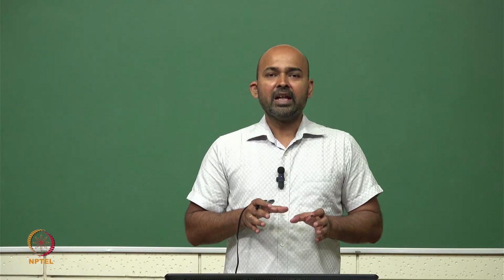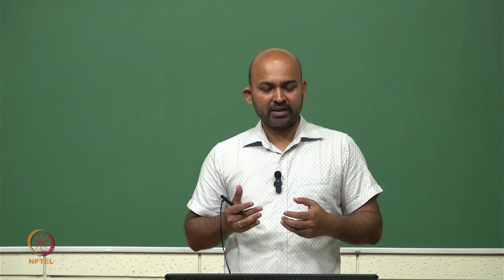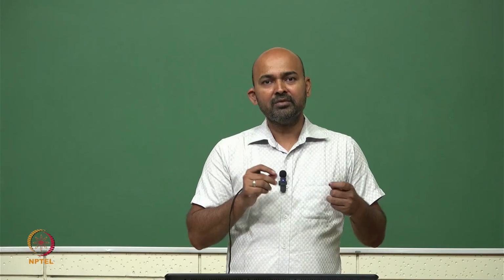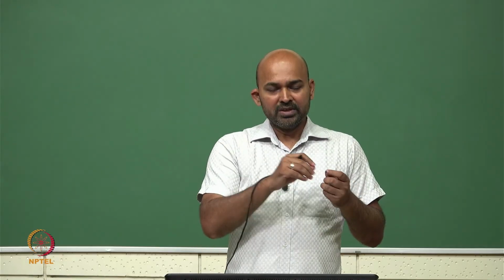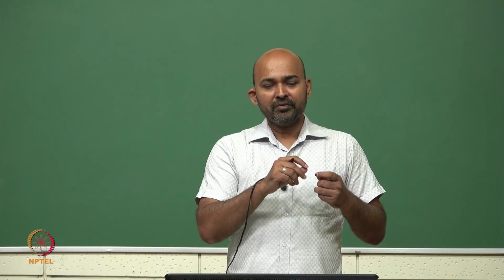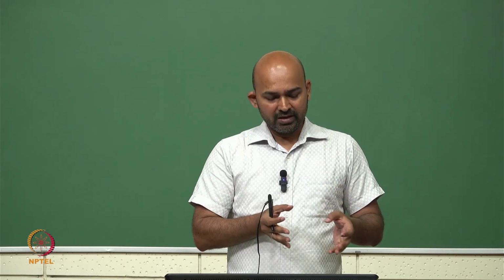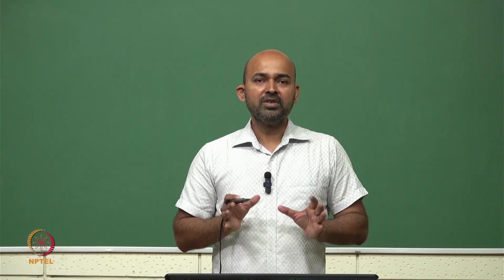So, these are some basic circuit elements which we use inside our simulation programs to simulate our circuits. These are very basic elements. These are used to mimic various components. For example, we want to mimic a wire which is used to connect one module to another module. Physically, there is a metal which will be routed. So, this metal may have some certain resistance. So, we can mimic that wire, the actual connection, using resistance, and similarly capacitance and inductance can be used to mimic other behaviors. These are the circuit elements we generally use in the simulations of our circuits.